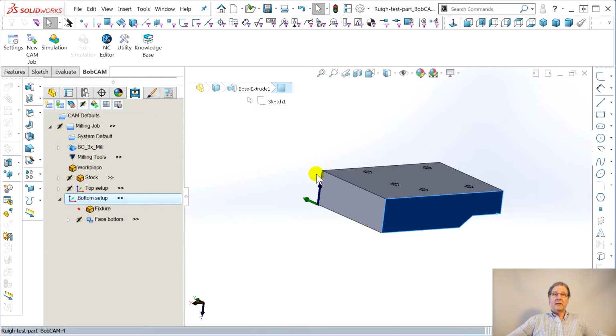I'm pretty sure I'd have to run it by my machinist pals, because the thickness of the stock is going to change how big the part is, right? All it knows is here's 0 and I'm going to go down so far. And so you can't count on the stock being exactly the same. You shouldn't, right? To make this part accurate, you want to reference part 0 on the flip side now, down here. And that was fairly straightforward.